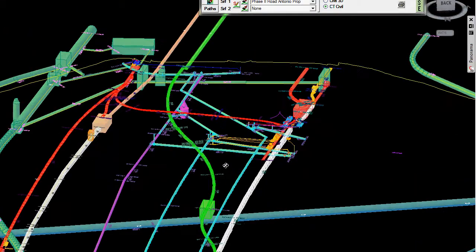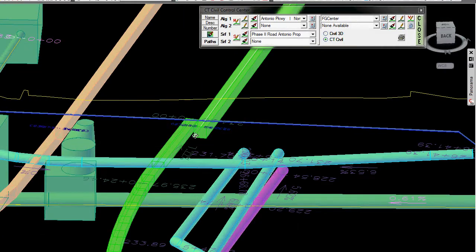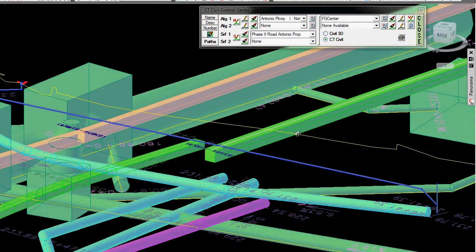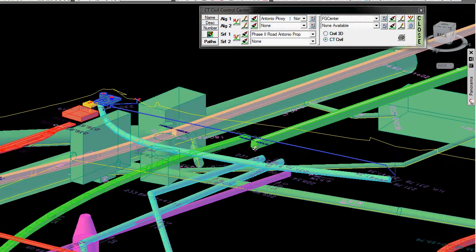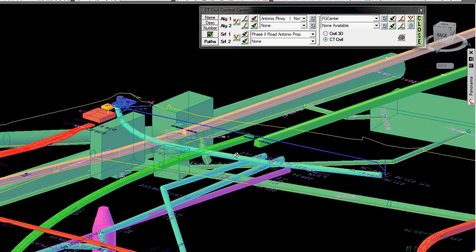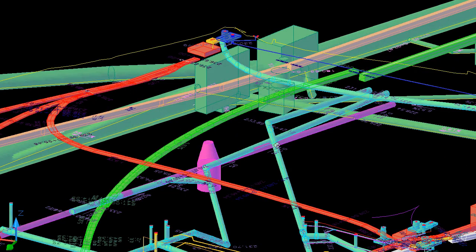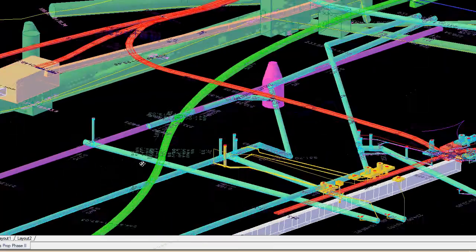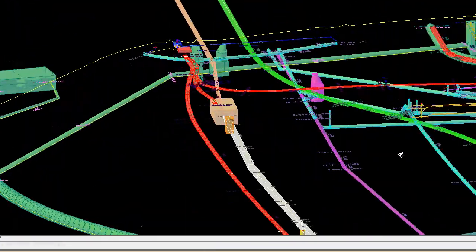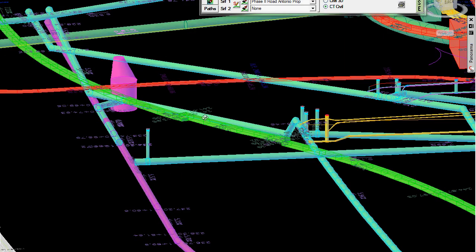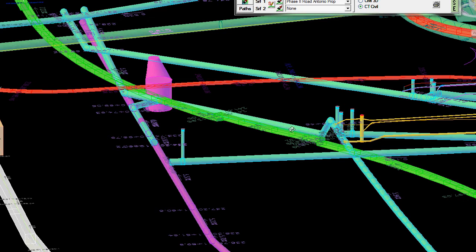There's a couple problems on this. First of all, this connection, that's no good. 30 inches of cover did not connect us with our line, which is actually coming through a bridge here. So that's a problem. The other thing is, if you notice in here, we've got a funny kink. Wherever we hit there's actually a median here, so the surface follows that median. So when you get a 30-inch cover criteria, it just follows that right up. Well, that's not reality. Nobody builds like that. You get the same thing on this side over here where the curve is on the side.